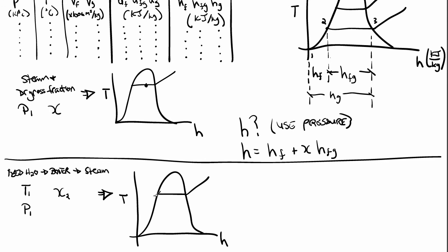Okay, I know where state 2 will be, of course, there. We know where state 3 will be. We always just mark those up. Oh, you know what? That is incorrect. State 3 is not there because we've been given a quality. Darn it. So we actually know that state 3 will be within the dome.